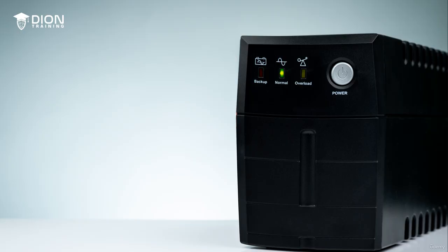While a UPS is a great device to use in your architecture to ensure your systems can remain online at all times, it is important to remember that most UPS units will only provide 15 to 60 minutes of power during a complete power failure. These UPS units are really designed to help prevent data loss or hardware damage during a sudden or short duration power loss event, and not going to be something that's going to help you for the long-term power outages.